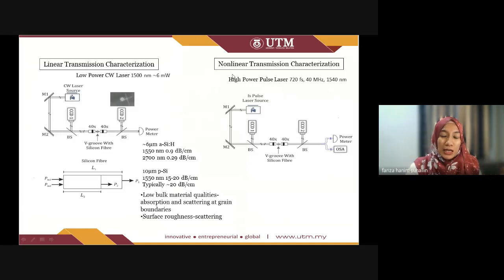But once we move to the nonlinear regime, we can use femtosecond lasers with a 40 megahertz repetition rate to give peak powers of around 450 watts maximum. So that's what happens if you want to characterize or probe nonlinear properties inside optical fibers. And we use the cutback method to get the value of nonlinear transmission, and